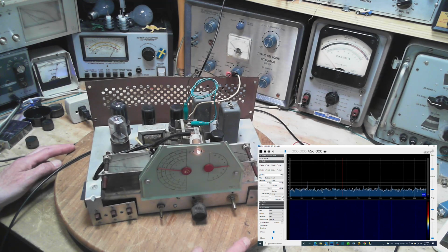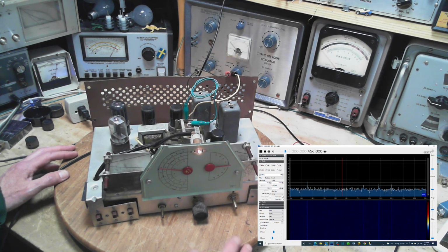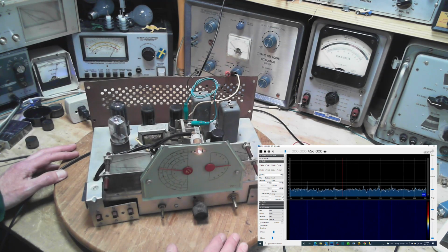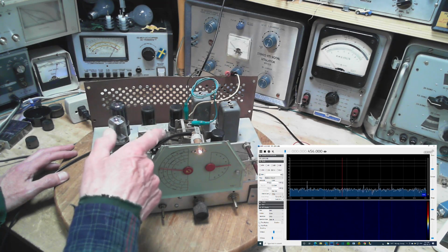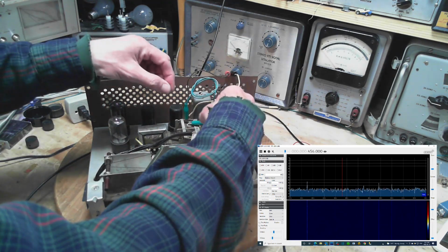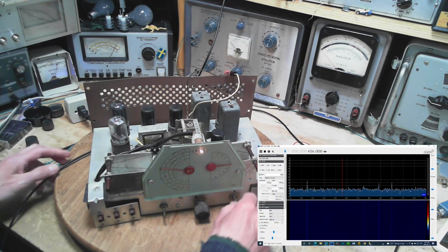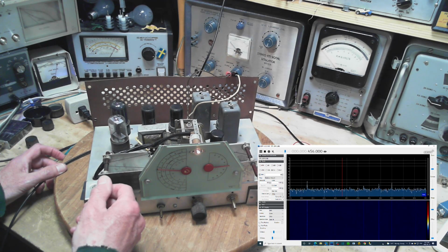Okay, so local oscillator's off. The only thing we should be hearing, is this really true? I think so. The only thing we should be hearing are frequencies at 455 kilohertz or thereabouts, and that's what we're listening to. You hear the kind of sound it is? Now, I didn't tune the radio. When I had the oscillator running, I could tune to a quiet spot and see if this is what you hear. Let's try that. Can we tune to a spot so quiet? It sounds totally quiet.